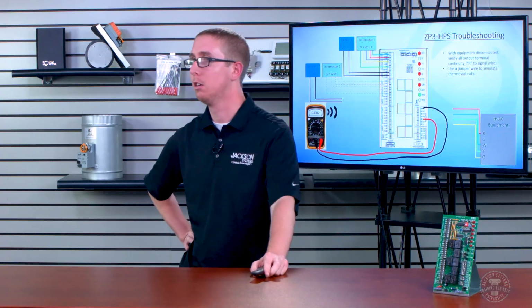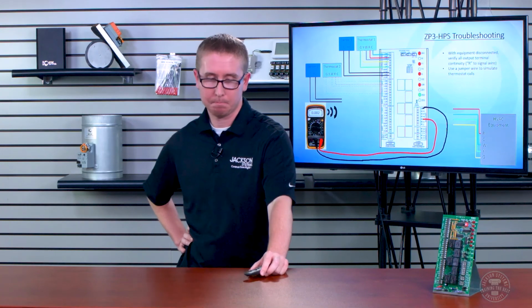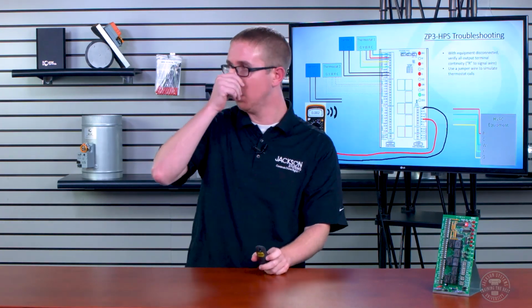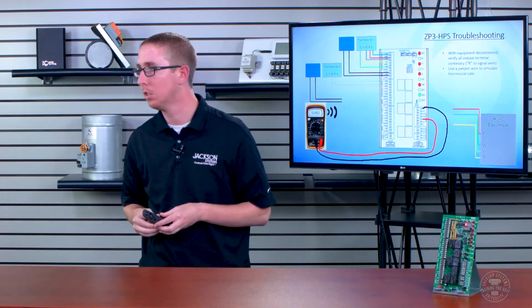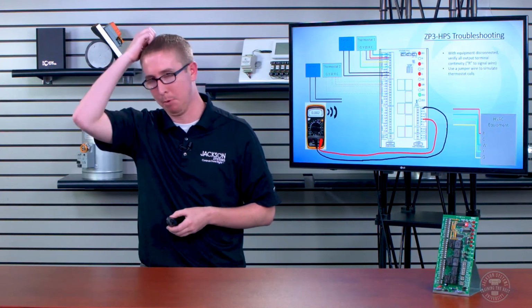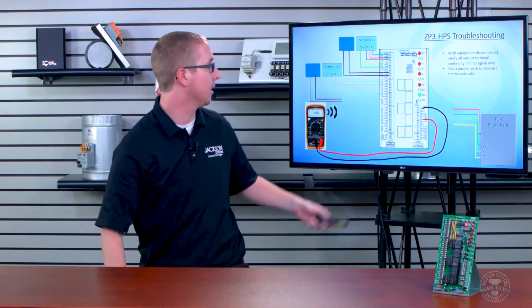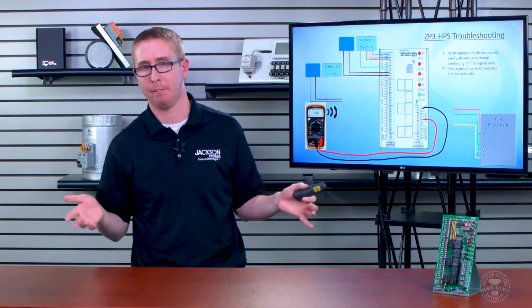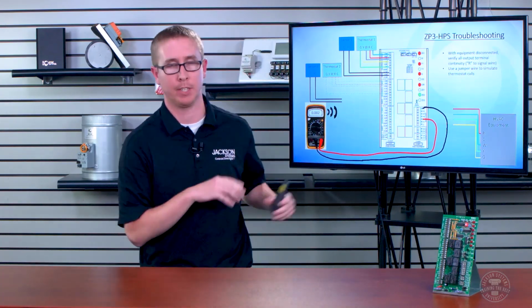They asked, could you explain the phasing procedure needed to set the control panel and the HVAC equipment transformers up properly? And I don't think you really need to phase the transformers. You're going to use two separate transformers. They're electrically isolated, so you don't have to phase the transformers. Tom explained it perfectly. They're electrically isolated because these are dry contacts. The two transformers do not need to be in phase. So you don't have to take that into account with anything we've discussed today.